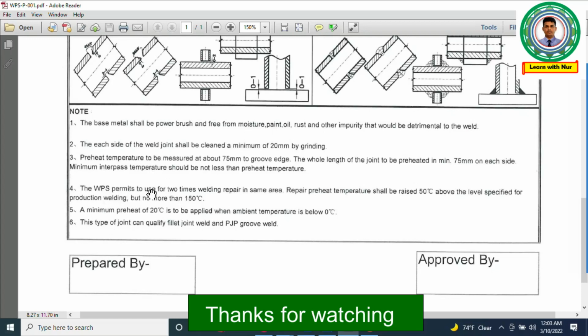The WPS permits up to 2 times welding repair in the same area. A repair preheat temperature shall be raised 50 degrees Celsius above the level specified for production welding, but no more than 150 degrees Celsius. So this is the note for welding repair. We can perform 2 times welding repair by this WPS. Then next, a minimum preheat of 20 degrees Celsius is to be applied when ambient temperature is below 0 degrees Celsius. Then this type of joint can qualify fillet joint welds and PJP partial joint penetration groove welds. So these are the things for this WPS.